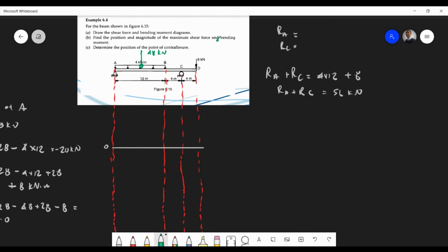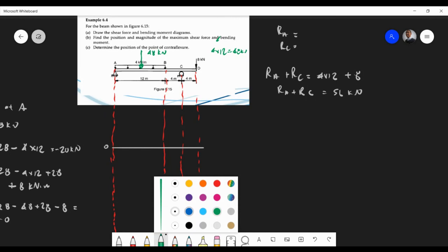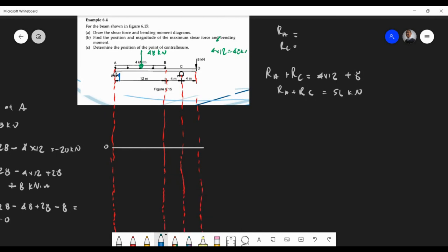And x is the distance to the midway point of the span it's covering. So then you can treat the UDL as a point load. From there, it should be fairly easy. I don't know if you're with me. Okay, no, I got you. So that's going to be RA and then RC, and you're just going to take moments. And Elisa, your question?